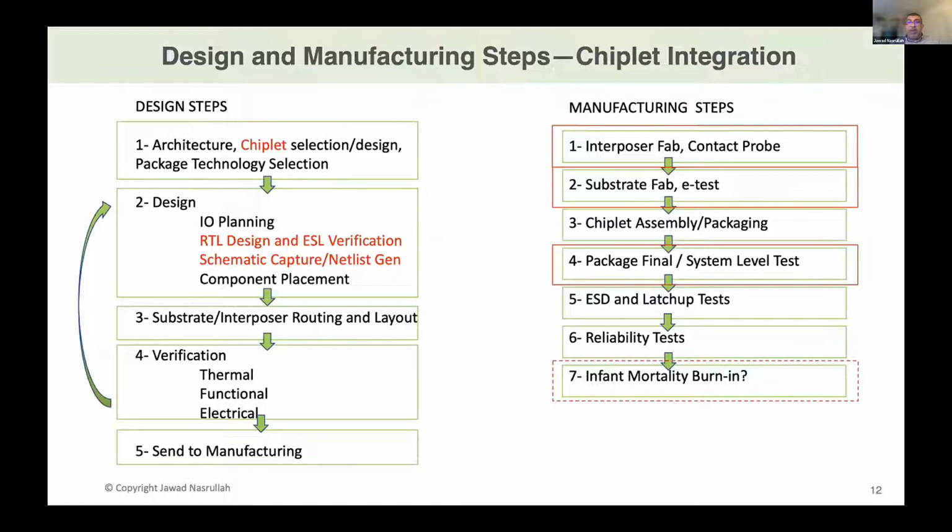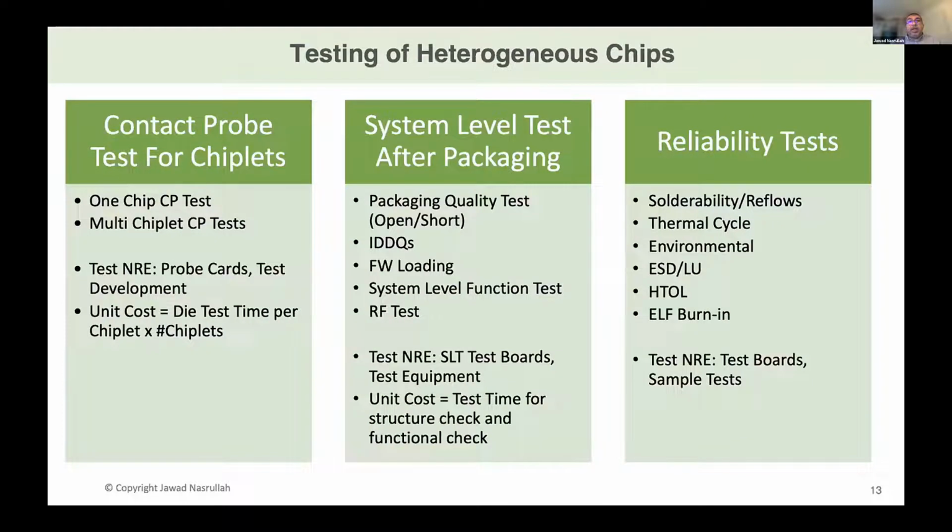When do we do burn-in? Do we do it in the components or do we do it after final assembly? It becomes pretty complicated after final assembly, but it may not be avoidable. So, individual results may vary, but from a cost point of view, if you can avoid it or push it back, it's a cost saver.